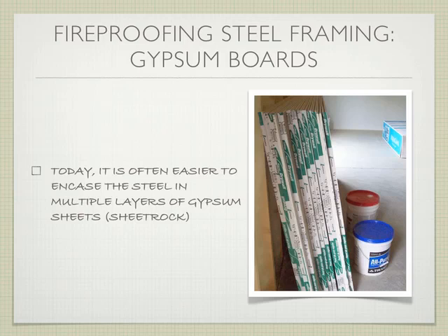So today we're not going to use lath and plaster. We're instead going to wrap these columns in several layers of sheetrock. The reason for several layers is not that the large face of the sheetrock is bad, it's that we can leak through the joints in the corners. Anybody a sheetrock taper? A few people know. You cover all of the corners with tape and mud, but that's not the same as the sheetrock itself.